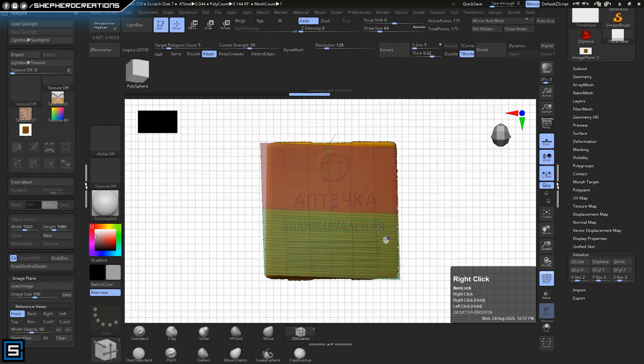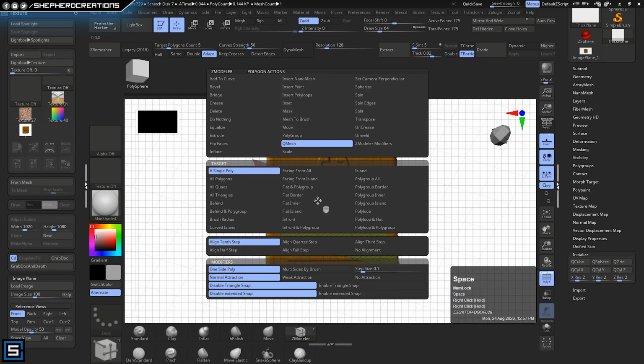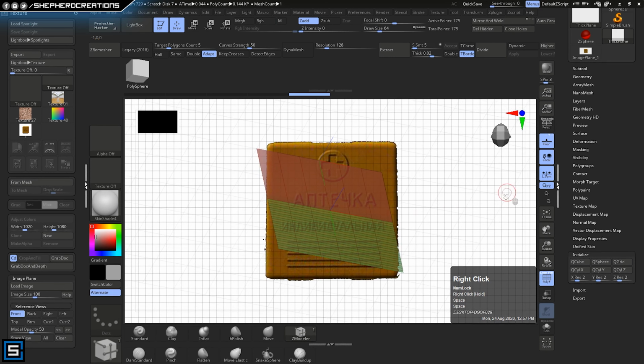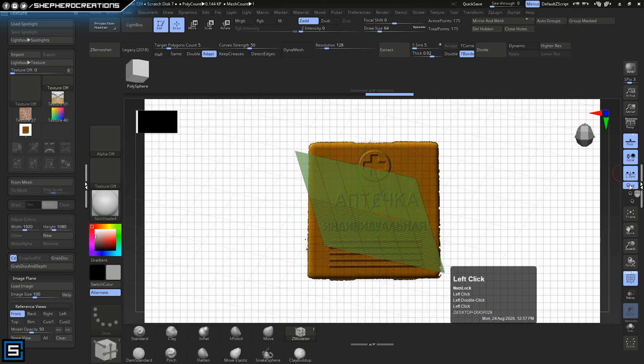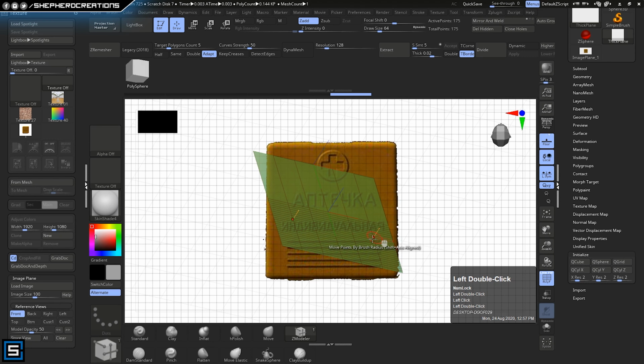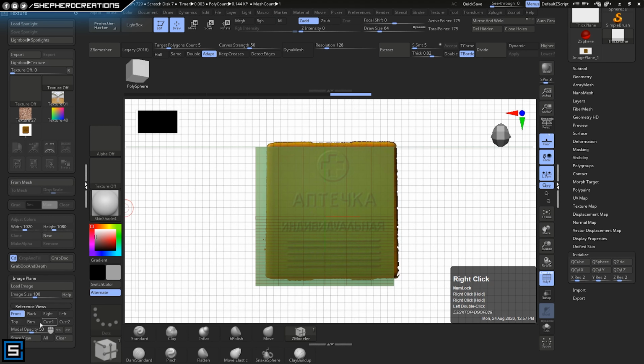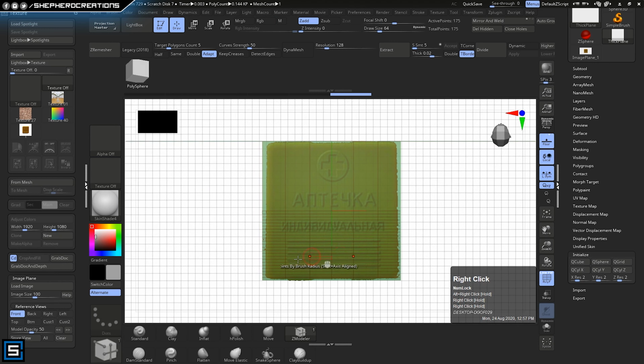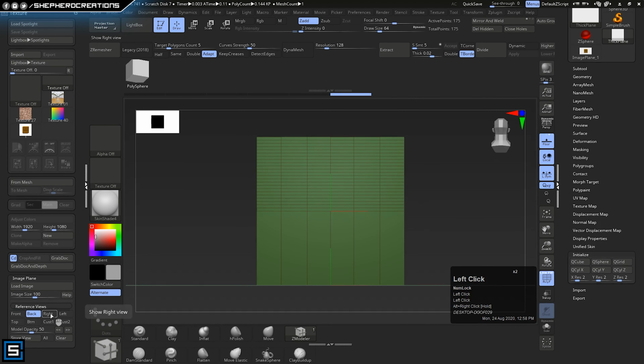I lined up those multiple poly loop lines on the bottom half of the model where I wanted them to go. Now I'm going to select Polygroup All. I'm going to go up to the top of my menu and select Auto Group so that it turns the entire model into one singular polygroup color. Then I'm going to hover over a blank polygon. I'm adjusting the image so that I know it's centered in the screen whenever I refer back to it.